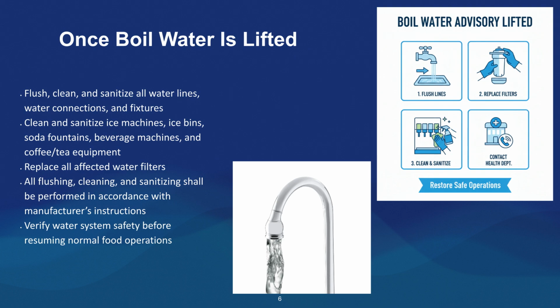Once a boil water advisory is lifted, flush, clean, and sanitize all water lines and fixtures. Also, clean and sanitize ice machines, soda fountains, and beverage equipment. Replace all affected water filters. Verify water system safety before resuming normal food operations.